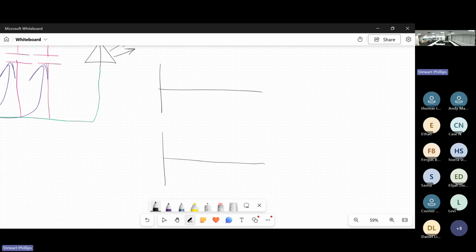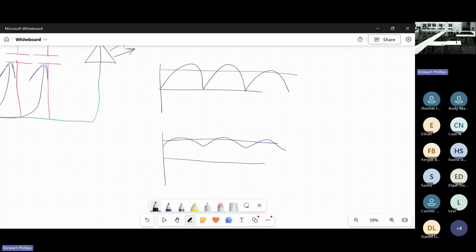Before the capacitor, we're going to get humpy or pulsating DC. What those capacitors are going to do, and this is our target voltage, if this is our target voltage, those capacitors, the more we add, it's going to end up being more like this. It smooths out the humps in our rectified DC. So we use it for smoothing. That's what we count it as. So we're smoothing out the DC waveform.